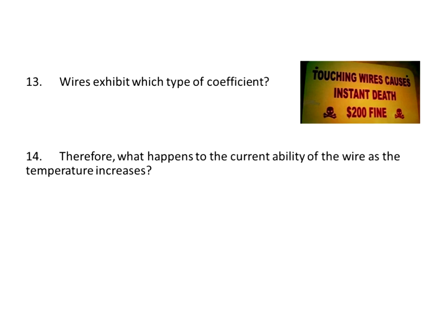Well, first you need to know, how does a piece of copper wire behave? Well, copper wire behaves like a positive temperature coefficient resistance. So what does that mean? Well, when the temperature goes up, what's going to happen to the resistance? Well, the resistance will also go up. So wire, when it gets hot, it increases its resistance.